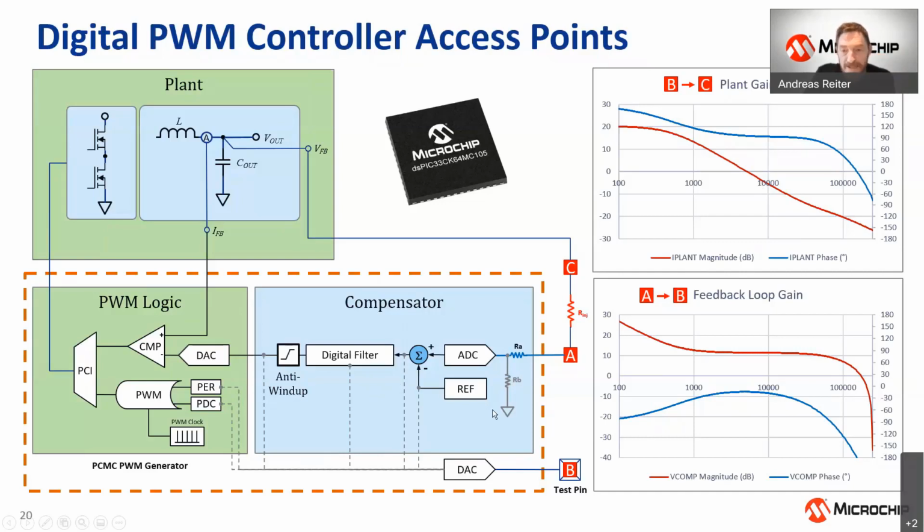Every device has DACs on board, and the DACs are quite fast, and they can be programmed with any kind of numerical value. You can usually adjust it in resolutions of up to 12-bit, and that is the resolution you can expect. For the system itself, this makes total sense because this is exactly the resolution the device is capable of seeing when it's using an ADC converter.